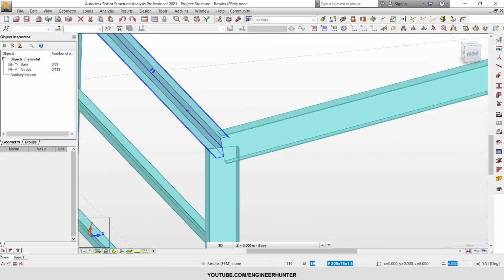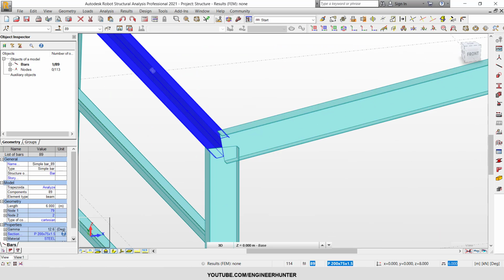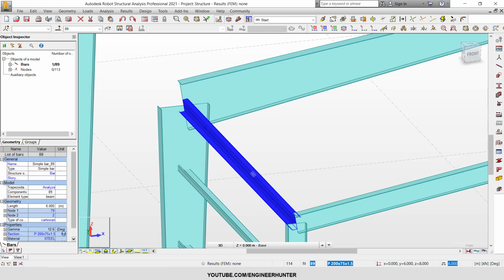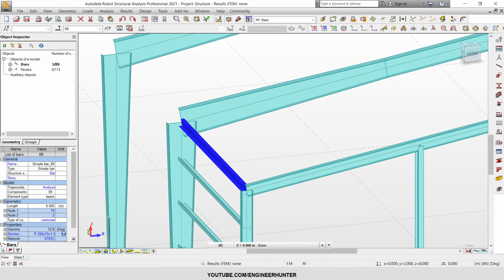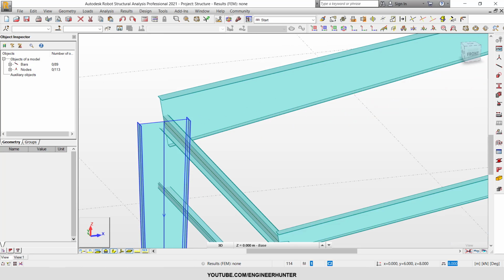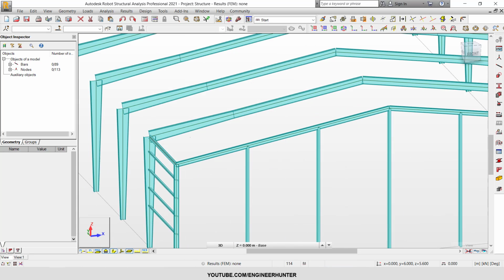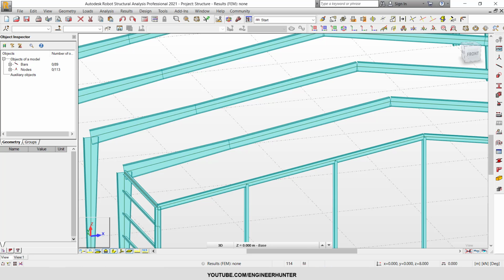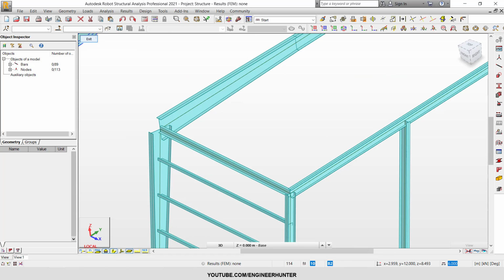As you can see, the beam is not at the 0 gamma angle like before. It's rotated a little bit. Its rotation follows our plane that we just created in view 1 here.